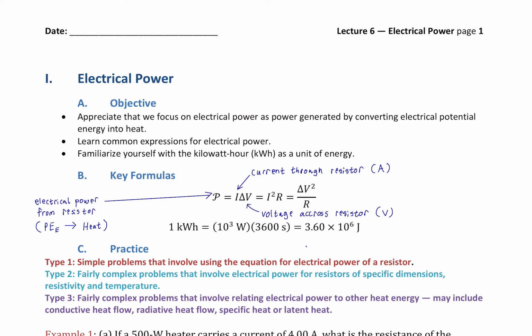That decrease in energy per charge gives us our power, as long as we know how much charge per second is falling off of that drop, going down that elevation change, which the voltage represents. So it makes sense that current times voltage, both through and across a resistor, is equal to the power that the resistor converts. You could also think of it as the power that the resistor outputs.